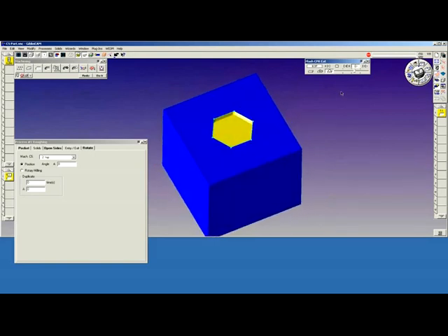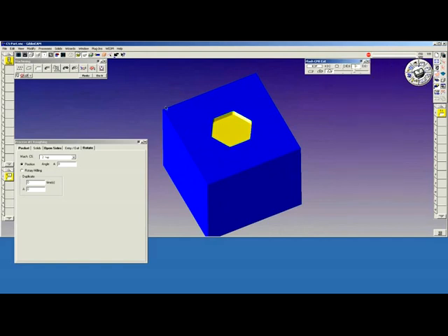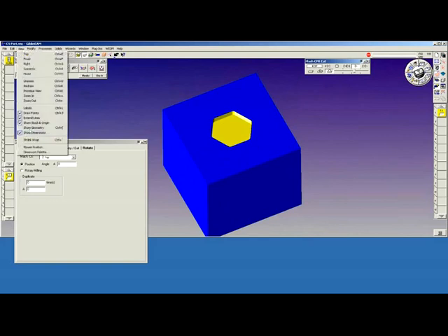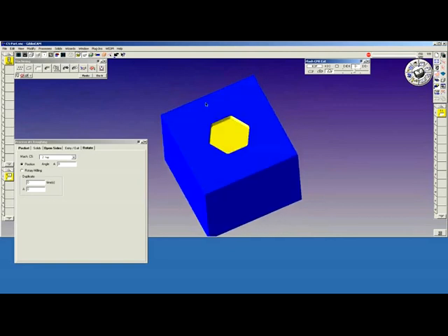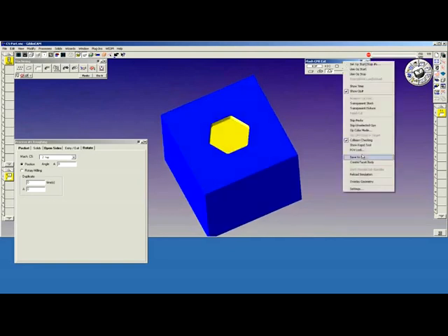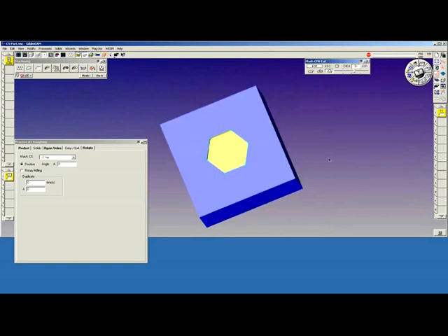If you don't want to leave it active, you can turn it off, and you can always go to the view menu and say show geometry, and it'll do the same thing. But if you use that method, the minute you move it, it deletes or erases the geometry. So sometimes I like to use the overlay geometry to ensure that I'm staying within the cut and that I'm cutting correctly.